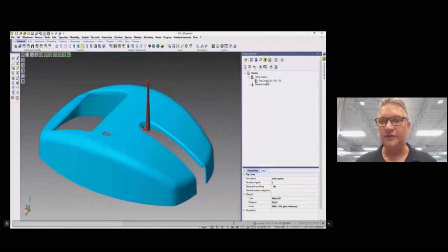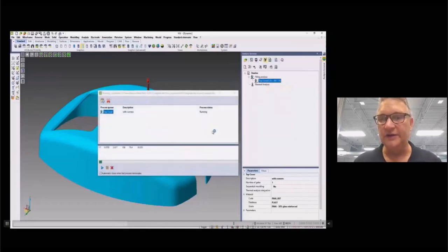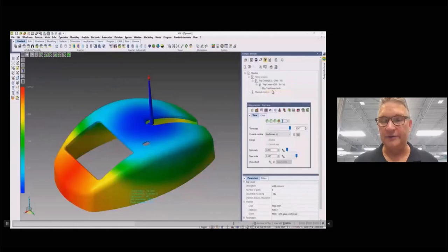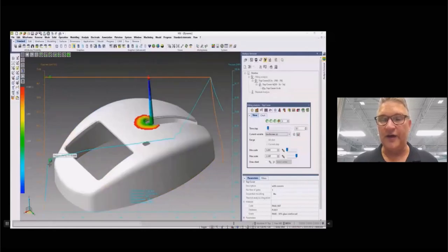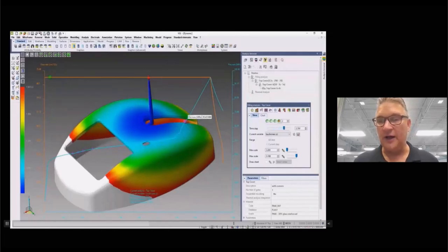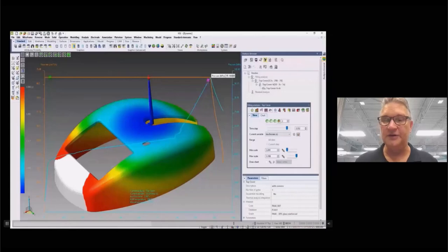After running a calculation, which is very fast, we can display many results. We can easily read, for example, the isochrone and how it shows the part filling. Displaying a graph chart, we can show the pressure required to fill the part, reviewing the crucial areas and evaluating the quality of the mold to obtain operational suggestions. Dragging the ball on the graph will show the filling simulation and the pressure at each point on the graph.